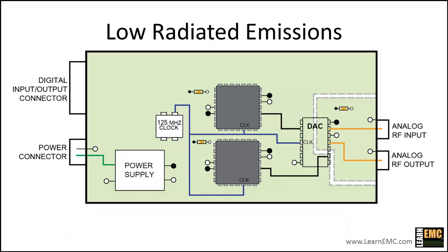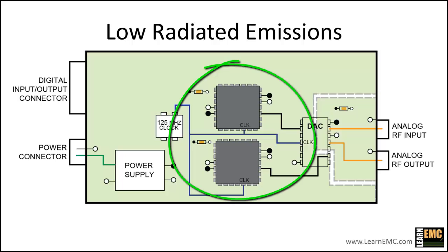So you may wonder why that gap was put in there in the first place. What the designers probably had in mind was that they wanted to prevent the noisy digital currents from returning on the ground plane under the analog devices and coupling to the analog signals.